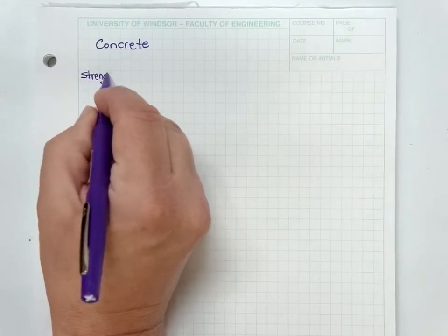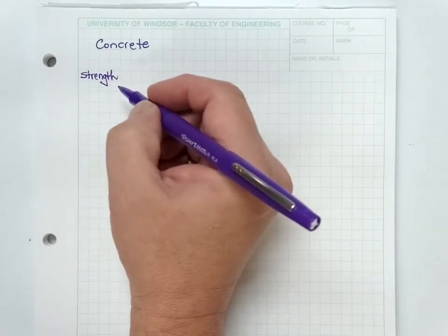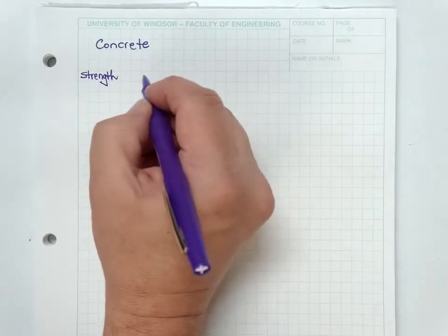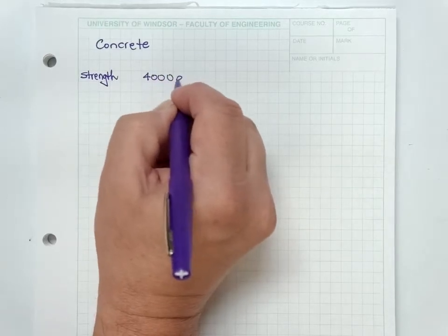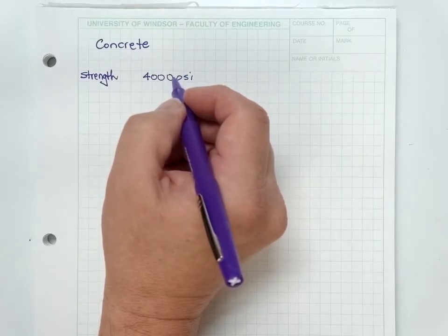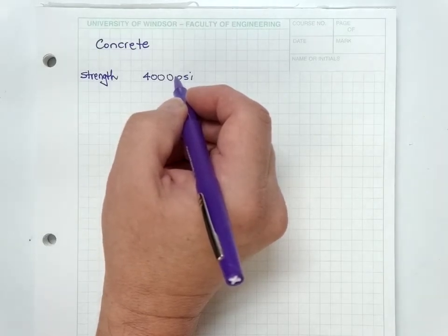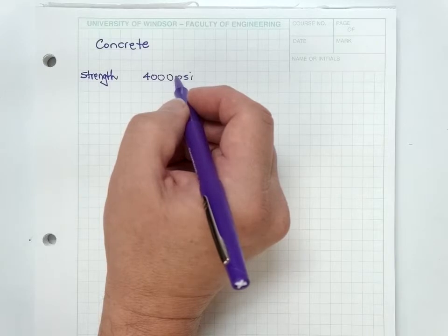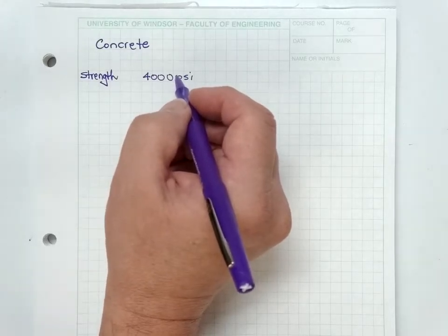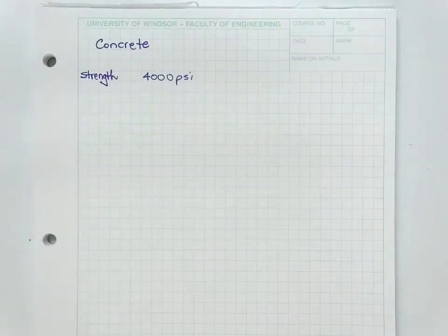You guys have been on construction sites. That's why I get you seniors. You've seen people order concrete. In fact, yes, sir. 4,000 psi. 4,000 pounds per square inch. Are most sidewalks at that? Yep, that's right. Concrete pad. Sure. Yeah, 4,000, very common structural material. The highway pavement out on I-94 that they've constructed there, specified strength is 4,000 PSI. So very common strength at 28 days, right?